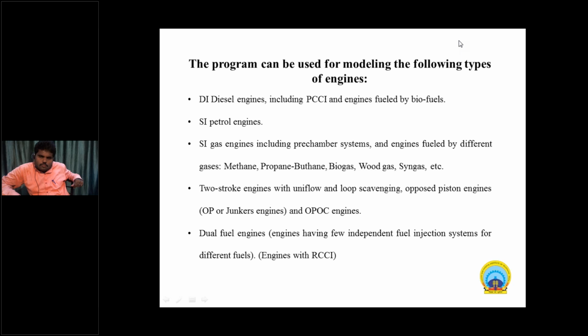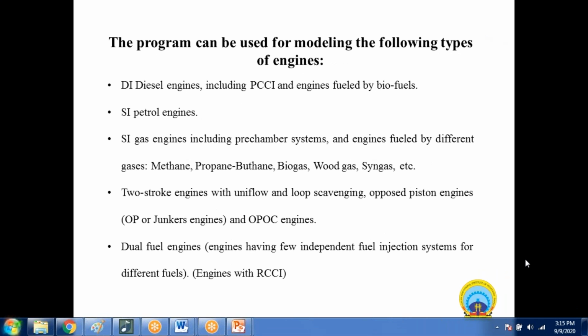So there is a chemical simulation. It also takes into account the effect of temperature, pressure, air-fuel ratio, and the EGR, that is our exhaust gas recirculation. So the above sub-models are integrated into the full cycle engine simulation software together with a library of non-linear programming procedures, allowing multi-dimensional optimization of the diesel engine. So this is the main point. The list of optimized parameters includes compression ratio, EGR, injection profile shape, fuel injection pressure, then mode timing, and boost pressure.